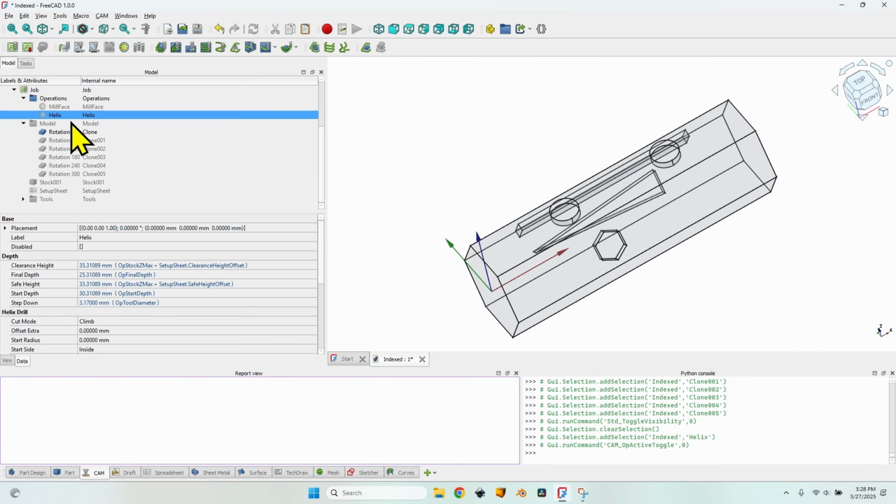But I forgot one thing which is very important, not in this step. In the initial step it can be whatever, but sometimes it happens the axis is not set to 0 degrees, and I want to start from that position, otherwise everything will get messed up. As I've told you, and as you might know, there's no such thing as moving the axis by default in FreeCAD, except for the 3D surface operation, which I'm not going to use. But I have an option which I'm going to take advantage of in order to have the correct rotation for the axis. You need to know a little bit Gcode, but it's just a basic command, a G0 command.